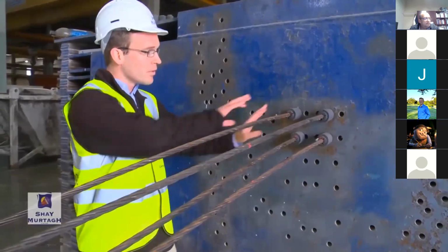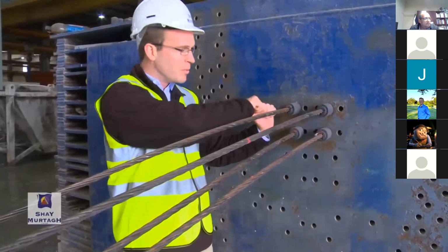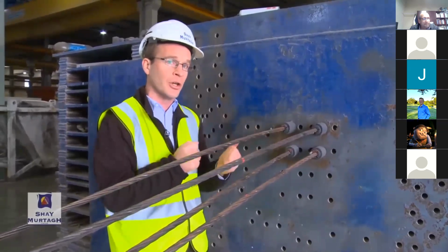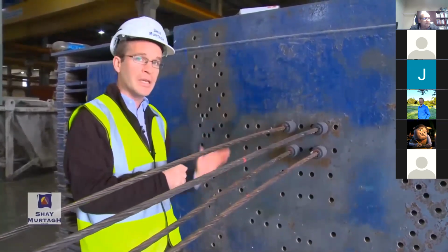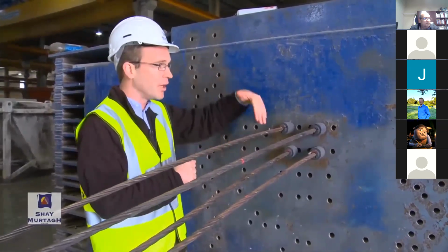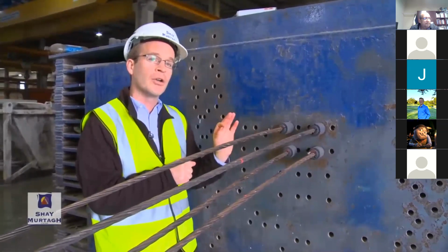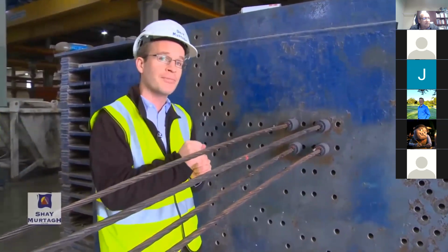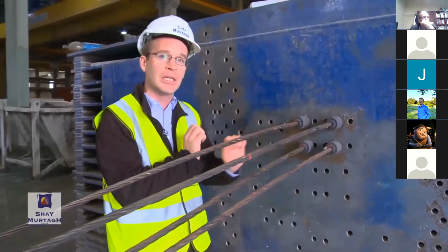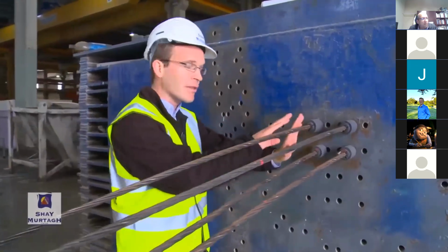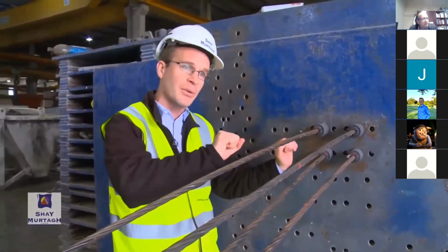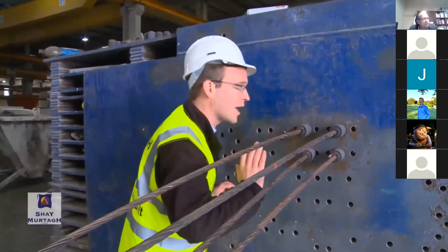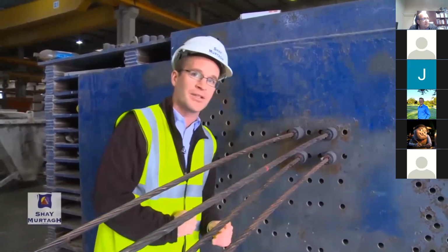So what we would do, these strands would be jacked up. They would be pulled back and they would be essentially stretched. They would be put into that very large amount of tension, 209 kilonewtons for these. The concrete would be cast around the strands into the appropriate cross-section. Once that concrete has reached the specified compressive strength, then the strands would be gradually released, thereby transferring that force that was in the strands when they were stretched into the concrete. So that very large force in the strands would then be applied as compression into the beam itself.